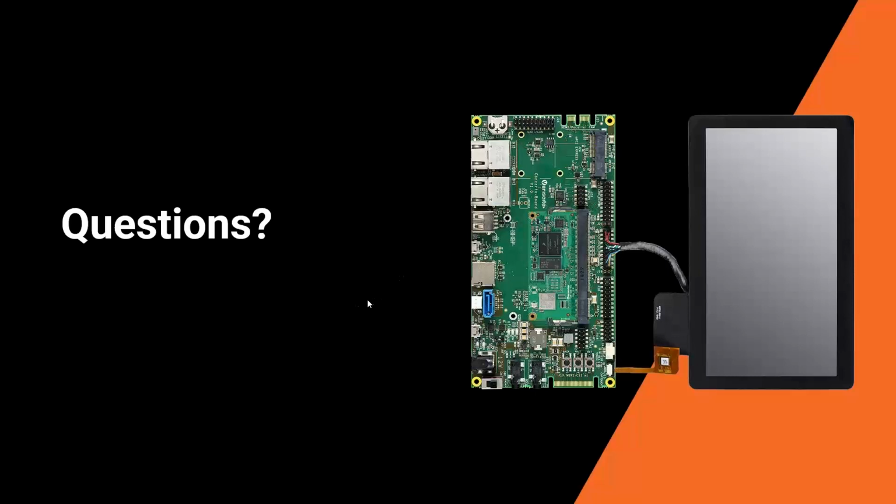Okay, another question. Does the kernel patch also exist for i.MX SoM? I suppose it was a mini or a nano, I don't know, but never mind. This patch that I was talking about in the beginning was specific for 6UL, and it's a patch that just changed the bits per pixel from 16 to 32.